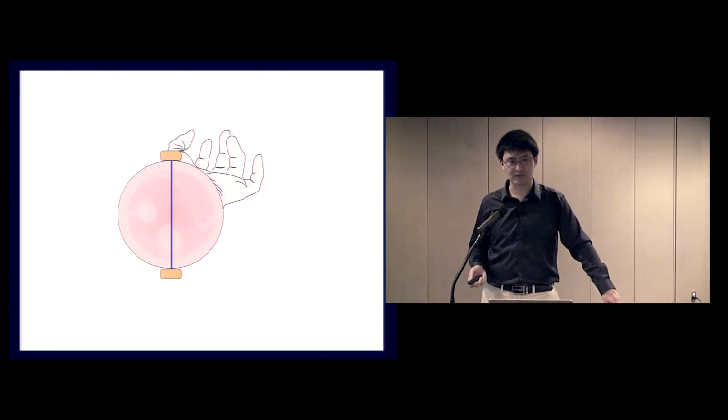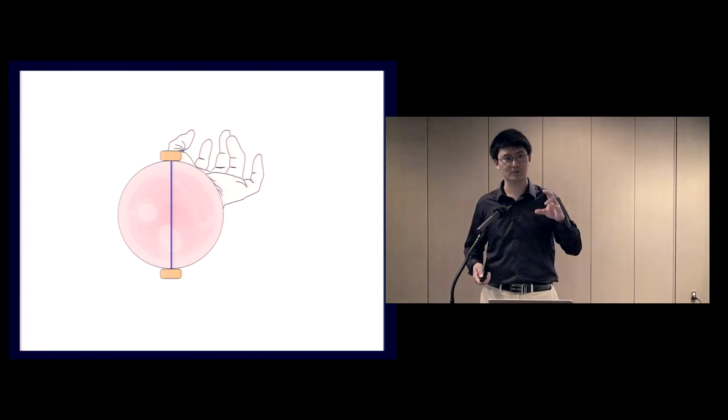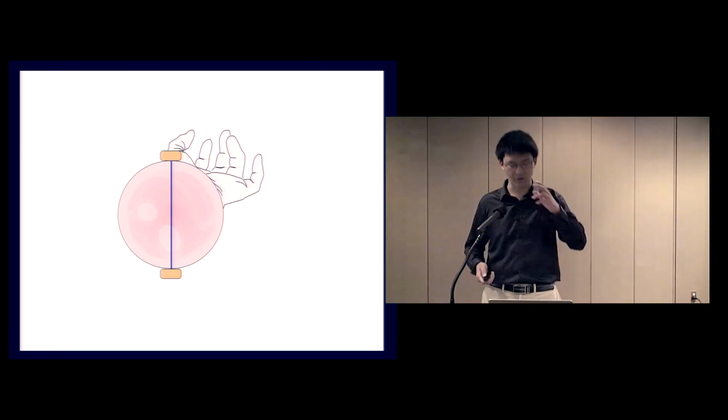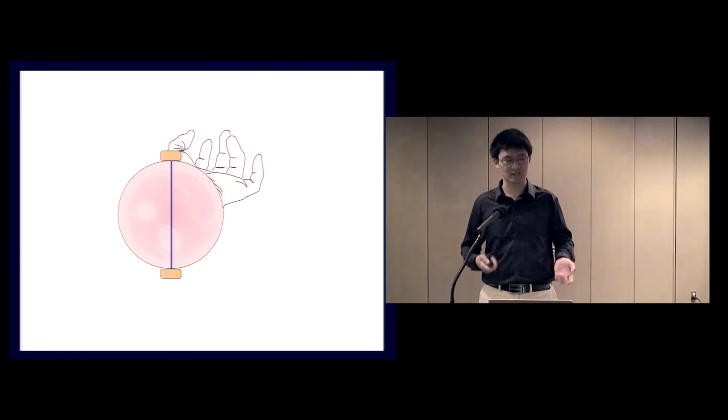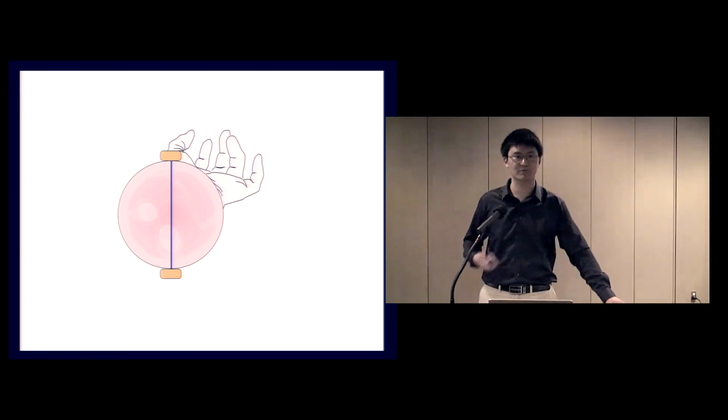The voltage of that signal is going to depend on the impedance distribution along the electrical path between those 2 electrodes. And so if we measure basically the voltage difference between those 2 electrodes, we can then infer the impedance along that electrical path, and we use the root mean square measurement in our system to smooth out those voltage fluctuations and actually perform that calculation.